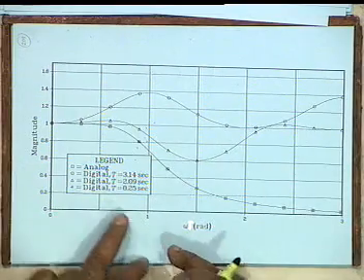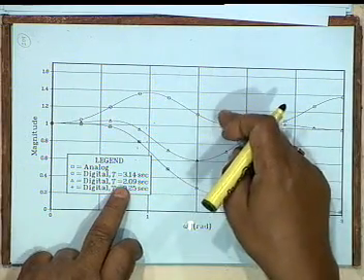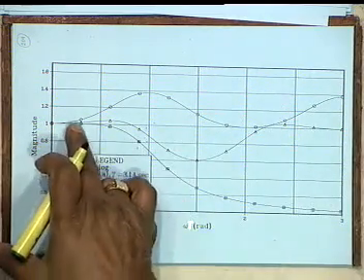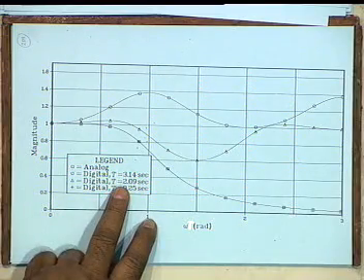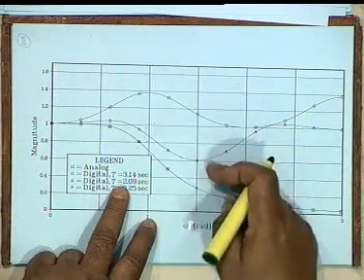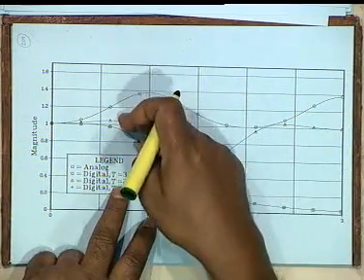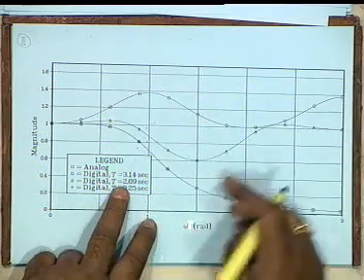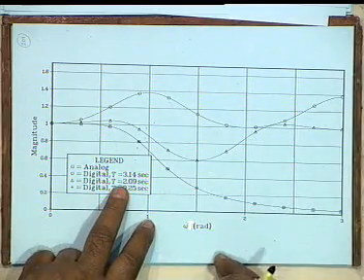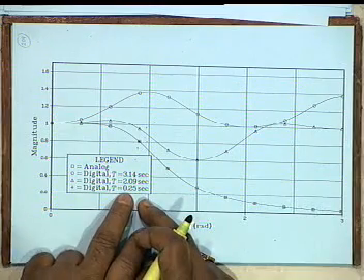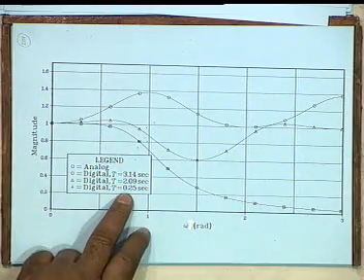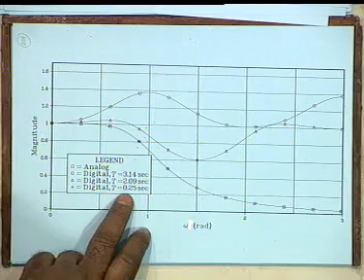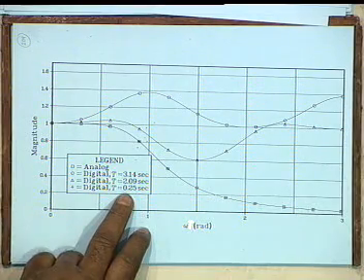Okay. Then capital T 2.09, that is, we reduce the sampling interval. This is what we get, this triangle. This is also not a low pass filter. Okay. The rejection is very poor, 0.6, also it has overshoot in the frequency response. Then again it goes up. But with capital T equal to 0.25 seconds, what is the sampling frequency corresponding to this? 0.25 second? 4 hertz. Why is it so small?